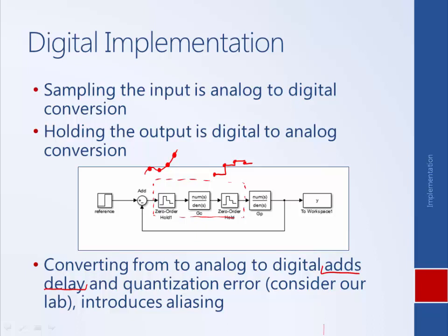And so by the end of that sample period, the sensor reading that we've used and the control command that we've generated is old. So we've basically introduced delay into our system. Whatever the sensor reading we had was, by the end of the sample period, it's now 10 milliseconds old. And similarly, whatever we commanded, by the end of the sample period, it's no longer the most up-to-date.